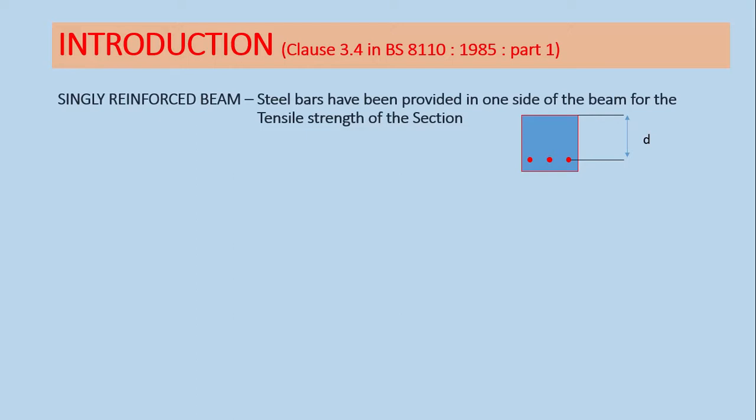beams, that bars. So you remember those top bars are not provided for compression forces, but in singly reinforced beams that is only to have a firm shape of the beam, so that we can easily cast in the site. So that is the main thing of singly reinforced beams.